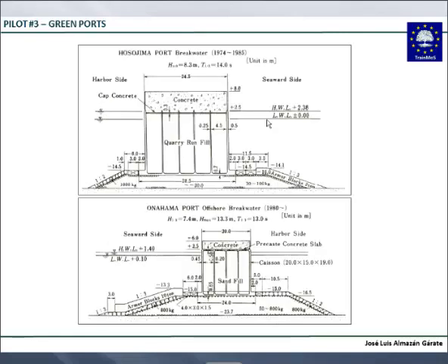Well, these are cases, these dikes in Japan, the coast of Japan, where you have a volcano, and in the Canary Islands, and you have the sea here. You cannot put a slope, because if you try to build a slope here, you cannot build it. So to build a dike here, you have to come to a vertical wall.